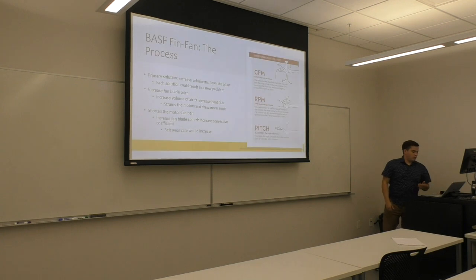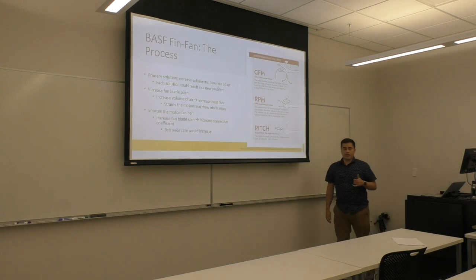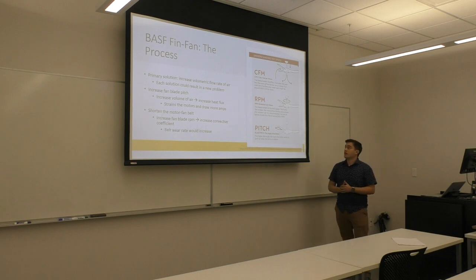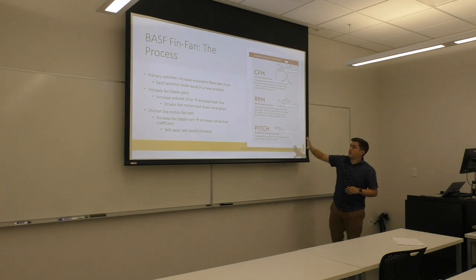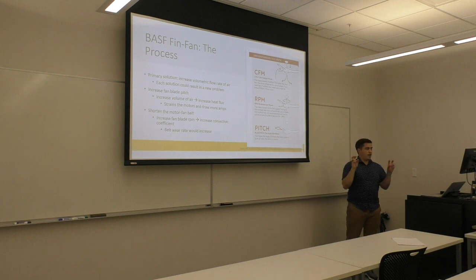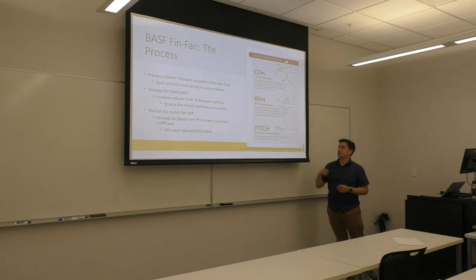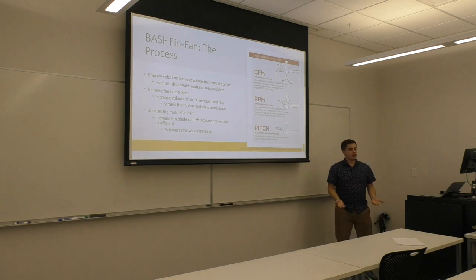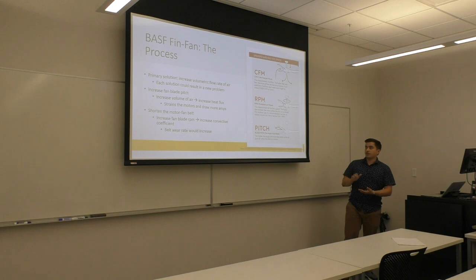And so, dealing with those components, you have three main ways to increase your heat transfer coefficient when it comes to convection. The main component is the amount of CFMs that you're able to push through, so the max flow rate of air essentially they're able to put through, and that's directly correlated with the RPM of the fans, so that's how fast that's spinning. Every revolution is another batch of air, so to speak, getting pushed through, as well as the pitch of the blades. As you increase the pitch of these fan blades, you're going to increase the amount of air that you're pushing through per revolution, as well as increasing the static pressure, which basically correlates to how well air can get through a dense fin array and push through it.